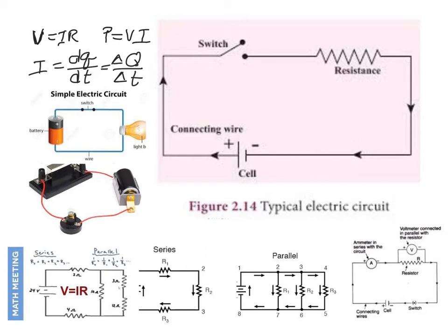Whereas voltage is measured between 2 points, the energy difference between 2 points, current is a flow quantity, and so it'd be measured like how many charges per second flow through the battery, through the resistor, through the switch. You go to a point, like you're counting traffic, and you count the charges that go past the point. And so when an ammeter is put in a circuit, and we'll talk about this later, you have to open the circuit and insert the meter so that the charges go through the meter rather than in parallel.